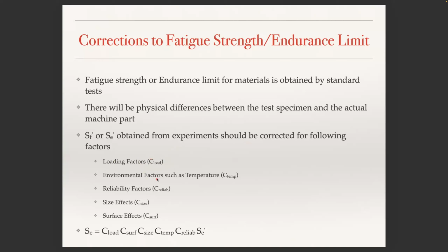Similarly, environmental factors. Suppose you are working at a different temperature range than what was used in the experiment, then you need to account for that. And because fatigue involves a lot of data, the fatigue data is known to have large spread, right? Because it's not very deterministic, unlike static loading. Unlike a regular tensile test where the data is highly deterministic and the spread is not very high, in fatigue the spread is very high.